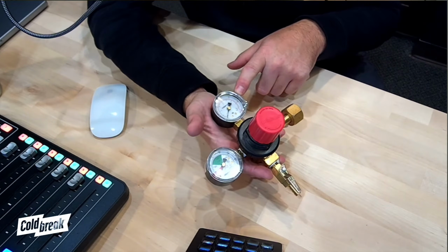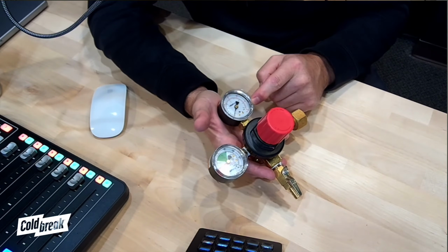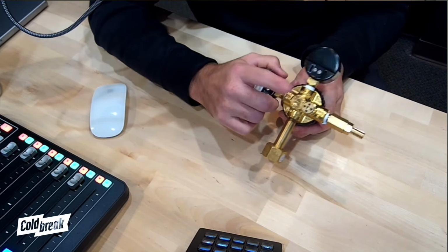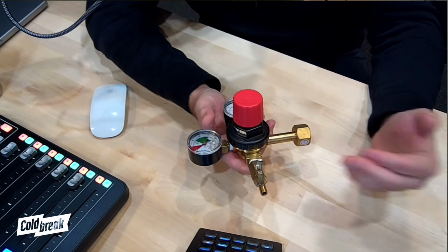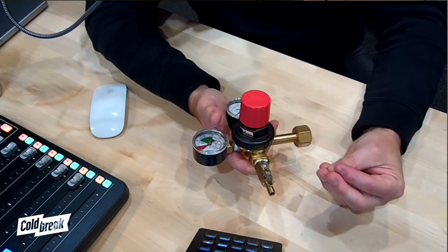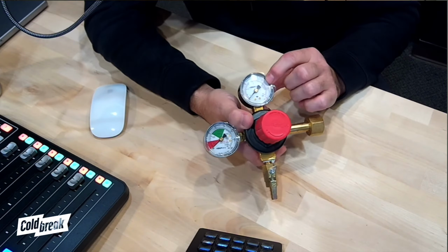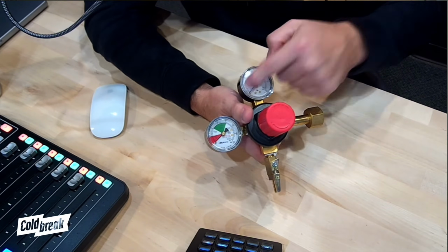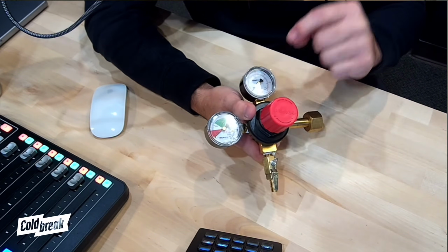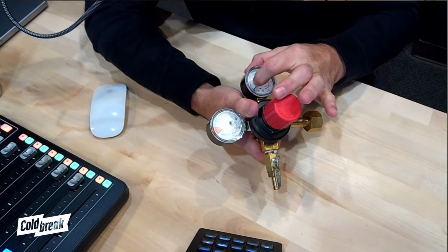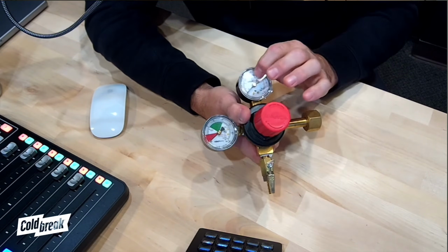The other one is the pressure gauge. 0 to 60 is all you need. You really won't go above 60 because, again, these will pop at like 52, 55, somewhere in there. And same with the beer couplers. Those have a pressure relief valve on them as well, and if those get too high, that pressure relief valve will pop. You can buy these with higher PSI, I think they go up to like 120 or 150. The problem with that is it's really hard to dial in how much PSI you need with a gauge that's higher. So we like the smaller ones.